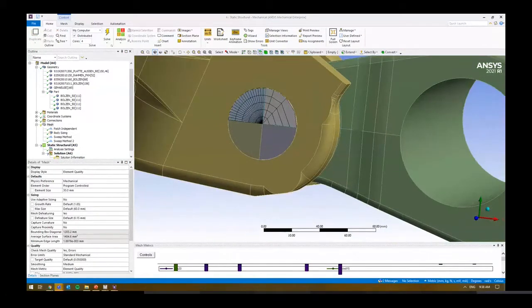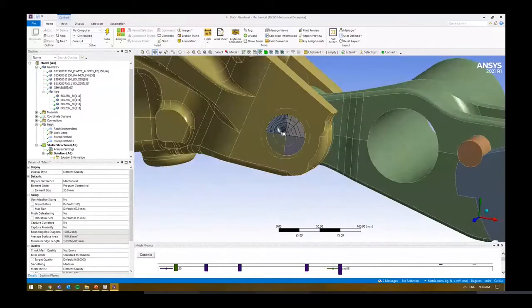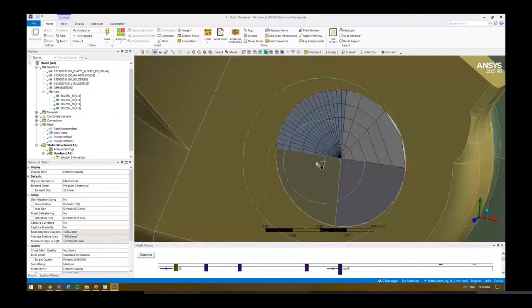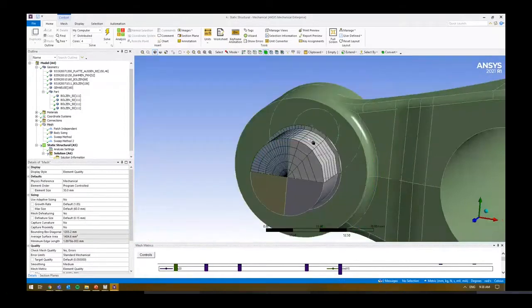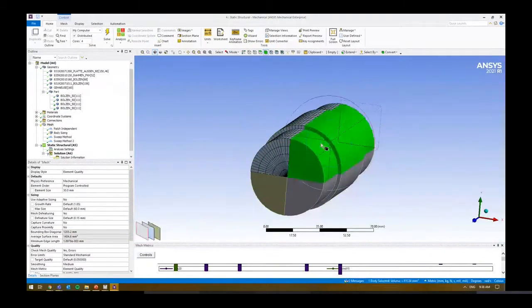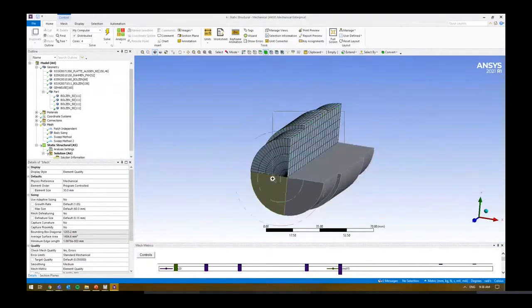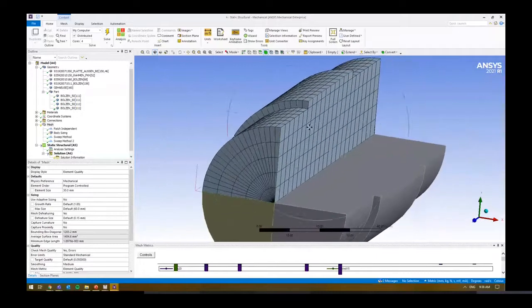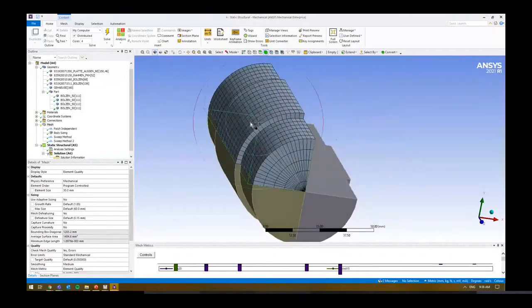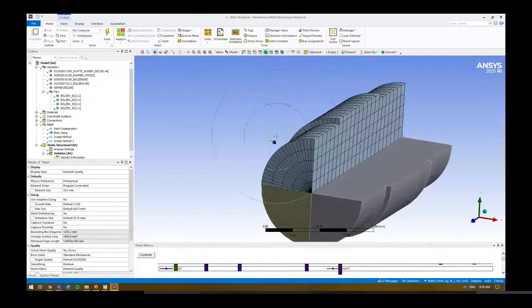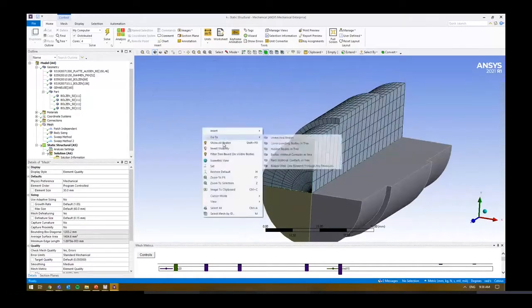How do you select the proper method according to the shape? So it comes down to a bit of trial and error. There's no easy way to just look at something and figure out if it's going to work. In this particular case, you can look at it and you can tell yourself, all right, I can take this face. I've got a clear axis. I don't have any holes or extrusions or anything like that. So that allows me to implement a sweep method.